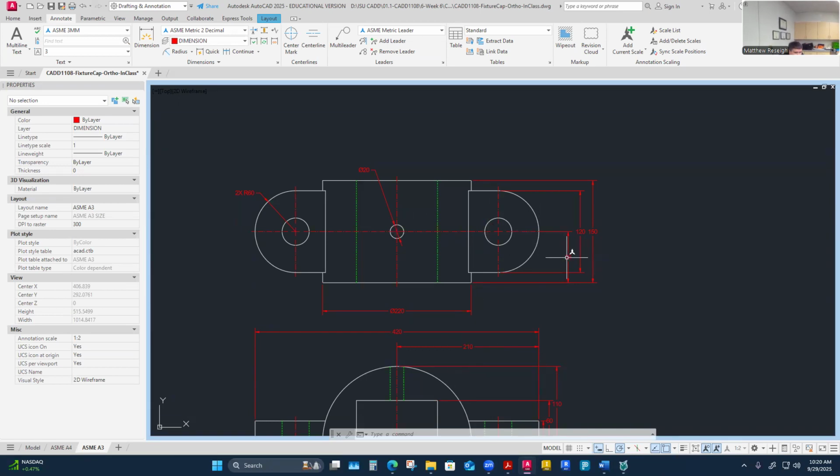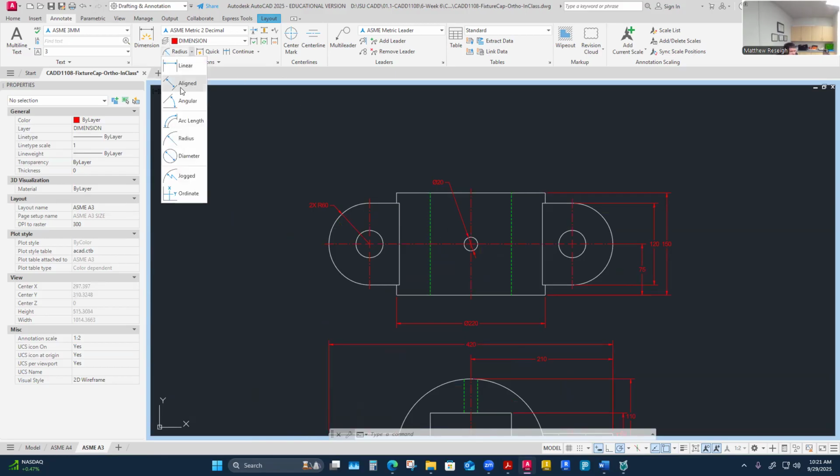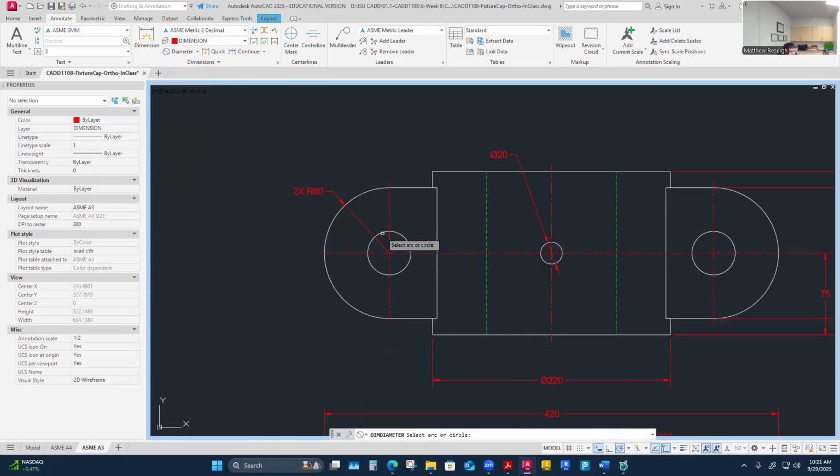Its location is again the 75, the center of the radius of that ear part. And 75 is now working almost three different locating dimensions. It's an ear location, and it's the whole location, and it's really locating the cylindrical part this way. So that 75 is doing a lot of work here. It's carrying a lot of locating. And so I think I'm going to move on to just the holes. And I think I'm going to put the other hole diameter over here and call it 2 times.